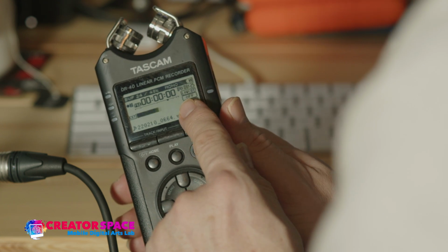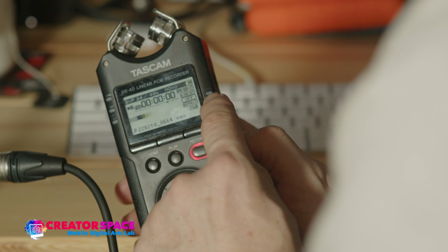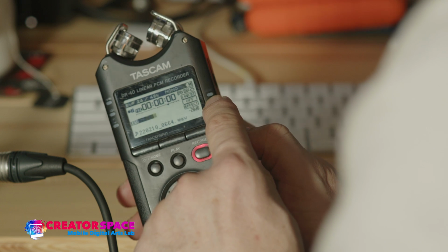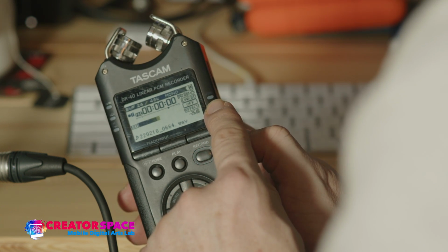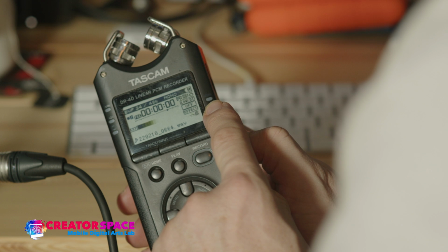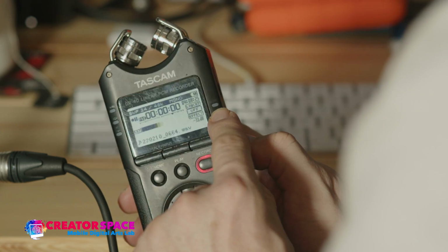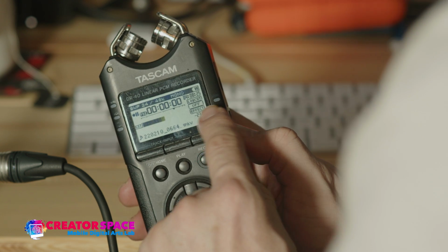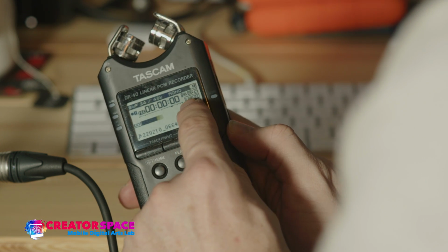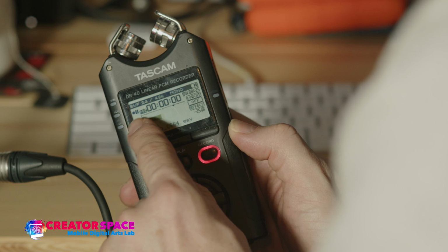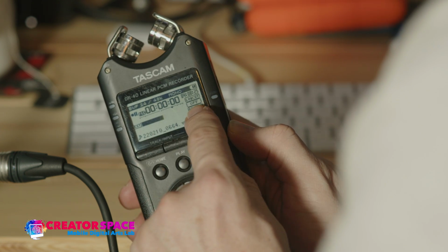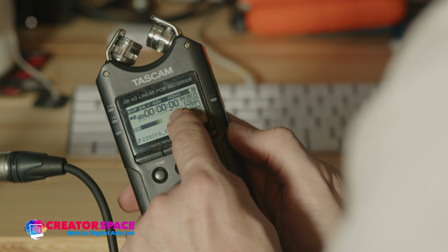And if you go all the way up, you're going to get this peak light, and it's the same thing on the Zoom. This peak light tells you that you're distorted, or peaking, or clipping basically. Distorted audio is no good. You won't be able to fix it, and it's unusable. So you want to always make sure you're never overloading it, that it never goes all the way to the end. So this is the meter, and this is showing you the levels of your audio. Ideally, you're kind of here at this arrow.